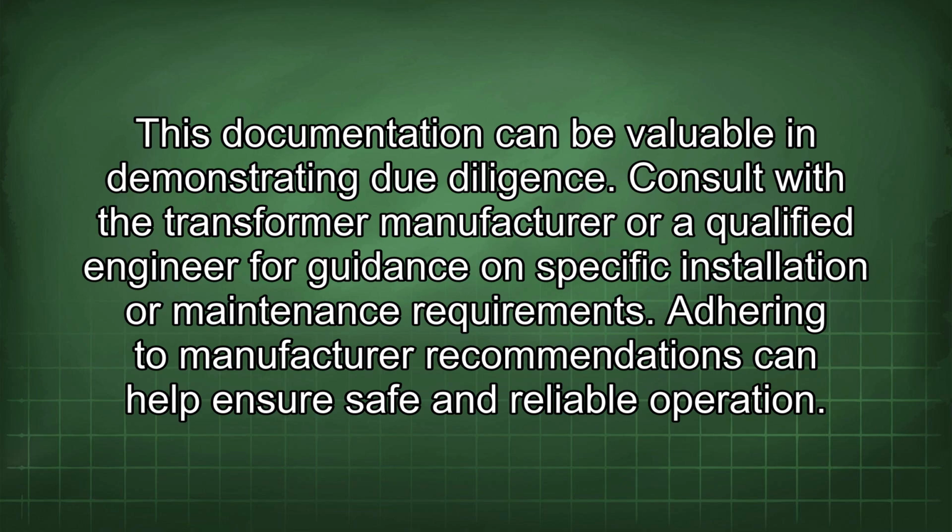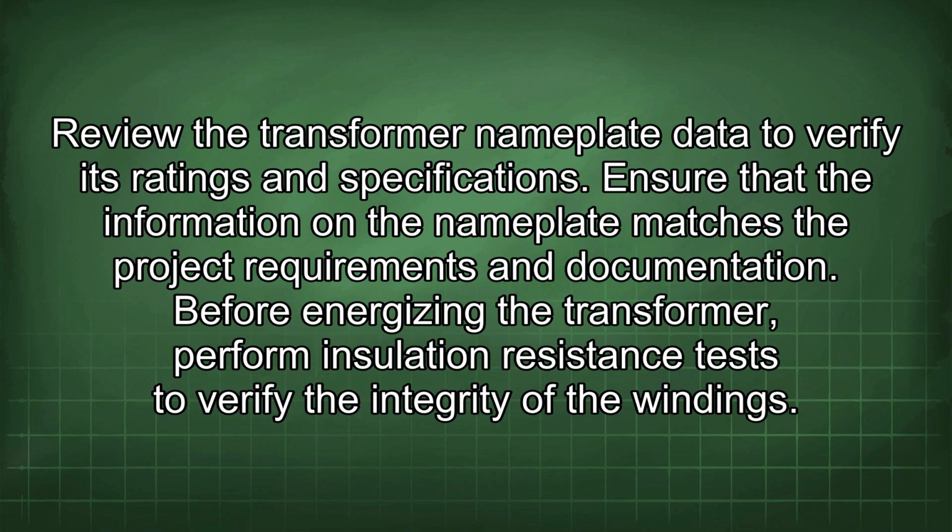Consult with the transformer manufacturer or a qualified engineer for guidance on specific installation or maintenance requirements. Adhering to manufacturer recommendations can help ensure safe and reliable operation. Review the transformer nameplate data to verify its ratings and specifications. Ensure that the information on the nameplate matches the project requirements and documentation.